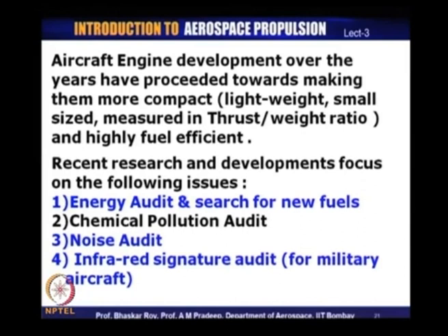We can say at the end that the various engine development over the years has produced more and more fuel efficient engines that start with high propulsive efficiency. They also are tending to be more and more compact with the various kinds of mechanical designs that are possible, and as a result the thrust to weight ratio, which is the final measure of their utility value for aircraft engines, is becoming higher and higher.